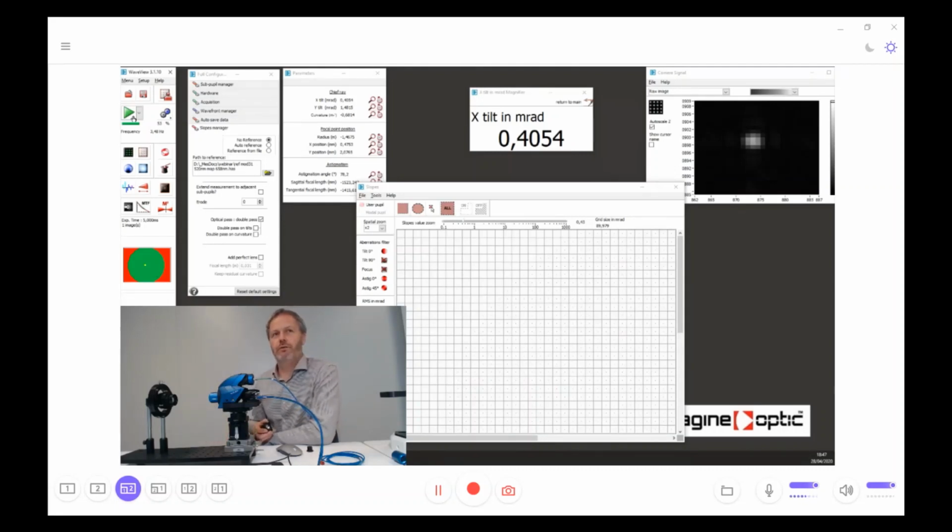Optics labs are usually stabilized at the level of plus or minus 1 degree C. And we know that with this level of temperature stabilization, there is no need for a new reference; a reference acquired at 20 is still okay for 21 degrees C. But of course, if we want to be very sure that everything is okay, whatever the temperature, you can redo this small reference measurement each time to be sure that the temperature does not affect the measurement you're doing. But that's the same for all technologies in wavefront sensing.